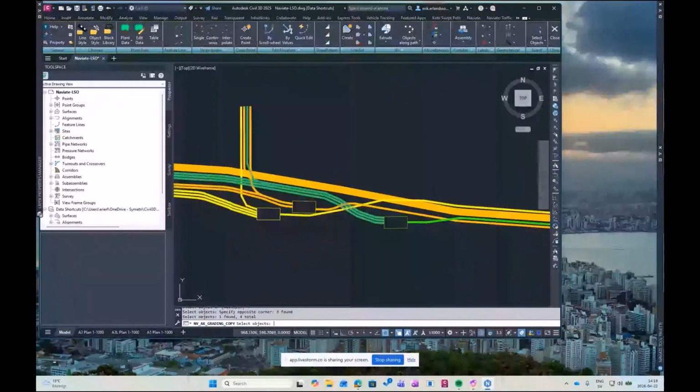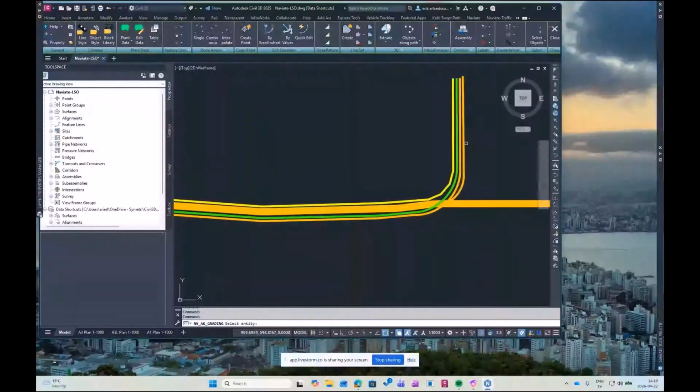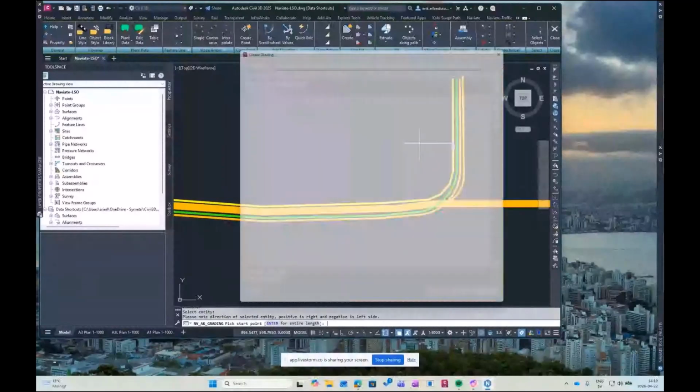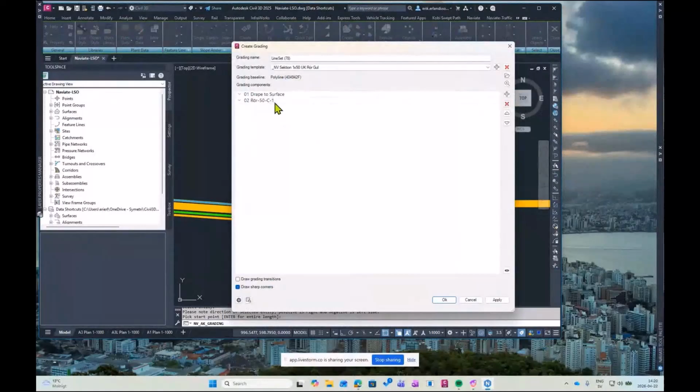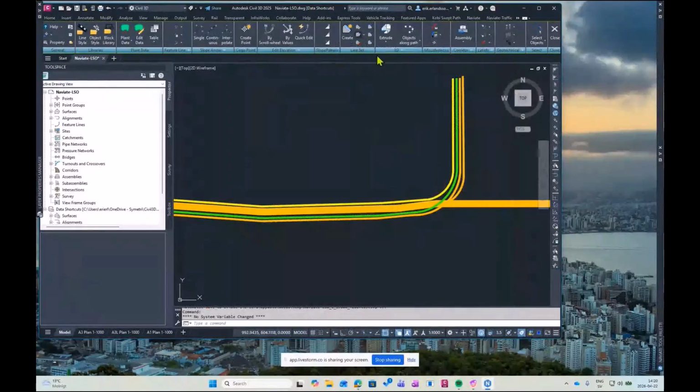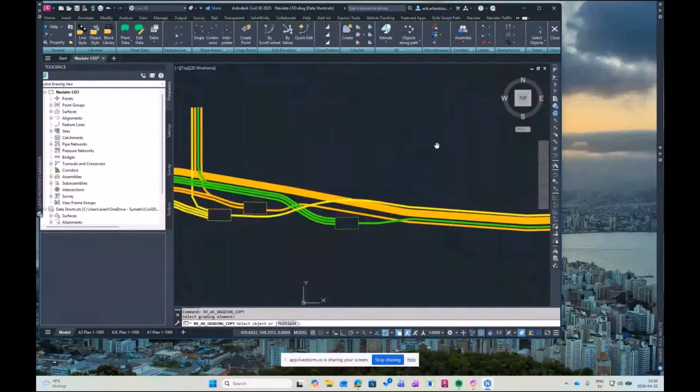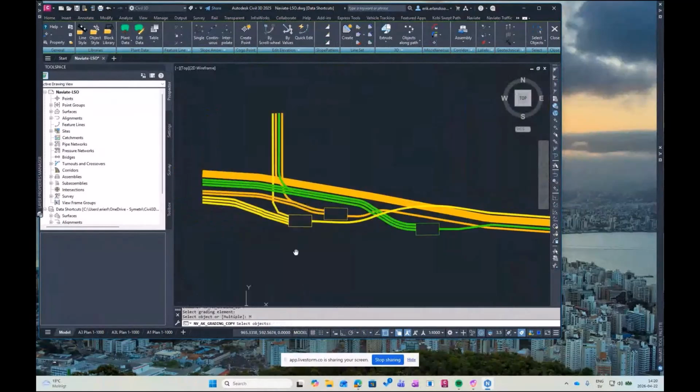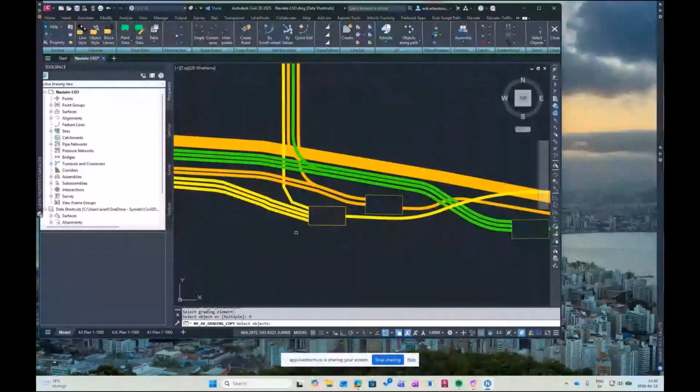And then we do the last one, the yellow one. So I click the yellow one, change it to the yellow template. These are all built in the same way. So it first drapes a line and then it puts the line for the pipe at the elevation that I have specified. So let's go enter there and then we copy the line set one last time. Multiple, and we do this.